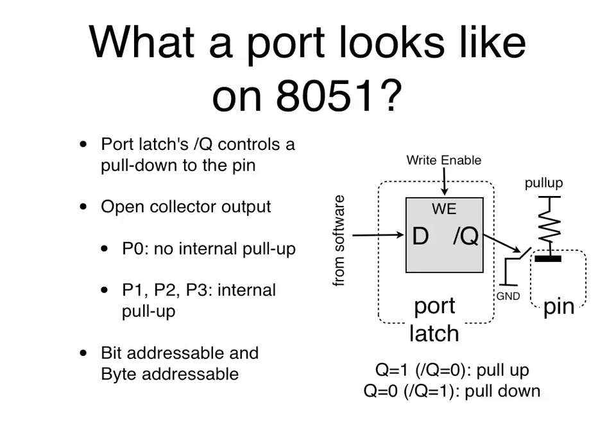Now, the output Q or Q bar, that's just a polarity difference. Q bar means the complement of Q. And remember, a lot of times these are just cross-coupled inverters, so you get both the Q and its Q bar for free, right? Because they are cross-coupled, you have both a true version and the complementary version for free, and it is just a matter of which one you want to make available.